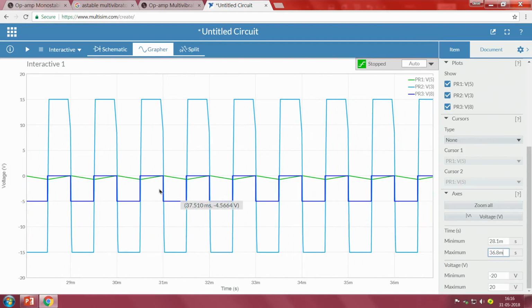So, what is happening? This is the voltage across the negative pulse that we are giving, and the duty cycle of the pulse is 50%. One thing we can see is that the capacitor is discharging, but not till minus 7.5. It discharges only as long as the pulse is negative; the pulse then goes back to 0. Because of that, the capacitor again starts charging, and again starts discharging. So, we cannot expect the same thing whatever we require.